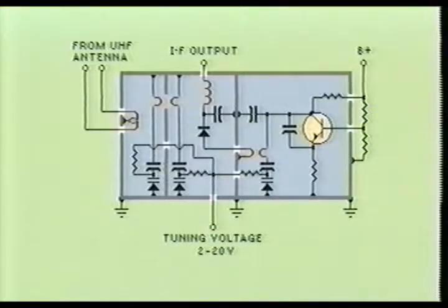Here you see a tuner module utilizing varactor diodes. Notice that the RF mixer and oscillator sections each have a varactor diode to properly tune each stage. Since all three stages must be tuned at the same time, a different form of ganging must be used. With no moving tuner parts, mechanical ganging is out of the question. Therefore, electrical ganging is used.